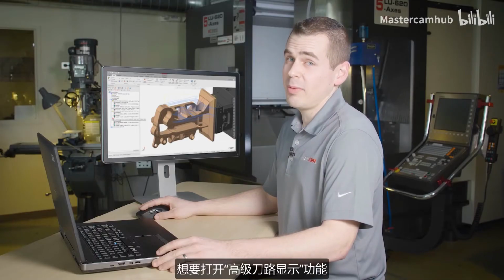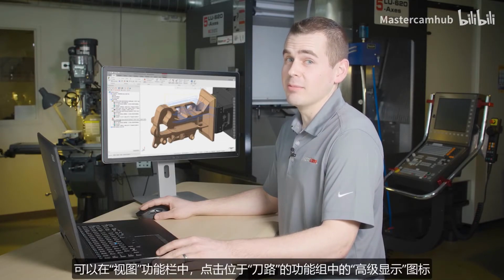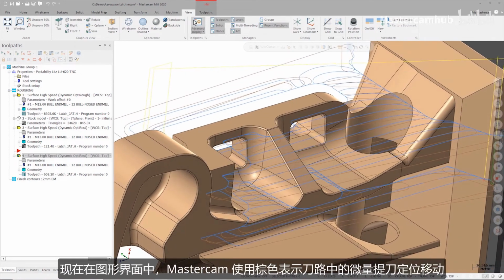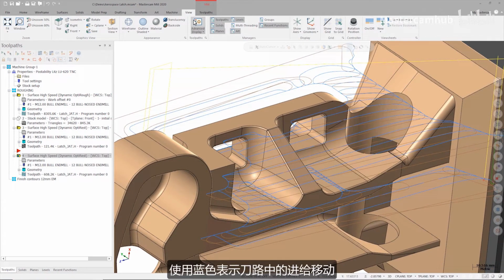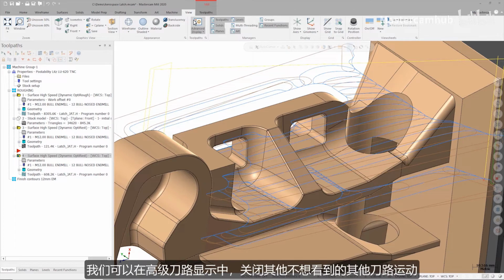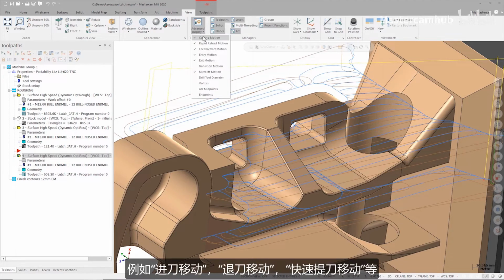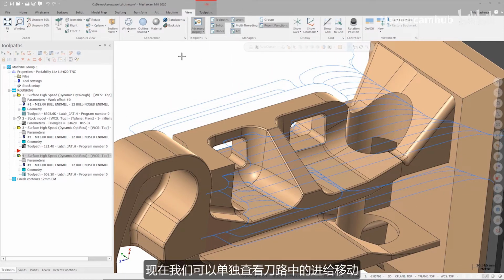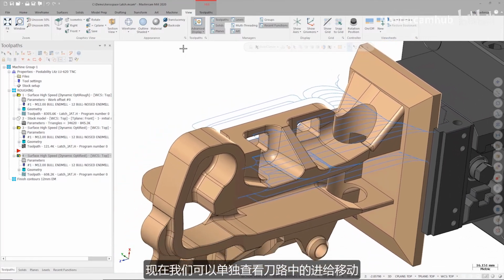To access Advanced Toolpath Display, I'll go to the View tab and click on the Advanced Display under the Toolpaths group. In the graphics view, Mastercam is now displaying the microlift repositioning moves in brown and the toolpath feed moves in blue. Let's concentrate on just the feed motion for now. To do this, I can turn off the display of any motion I don't want to see, such as entries, exits, and rapid motion. Now we have a clutter-free example of just the feed portion of our toolpath.